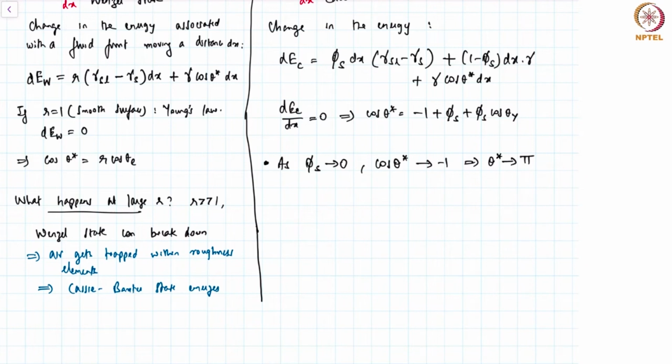So this is a case which you observe for many hydrophobic surfaces, including the lotus effect, where the effective contact angle appears like a superhydrophobic state, where the contact angle often exceeds 150 to 160 degrees. This is the kind of state that we observe when the area of the pillars basically shrinks.